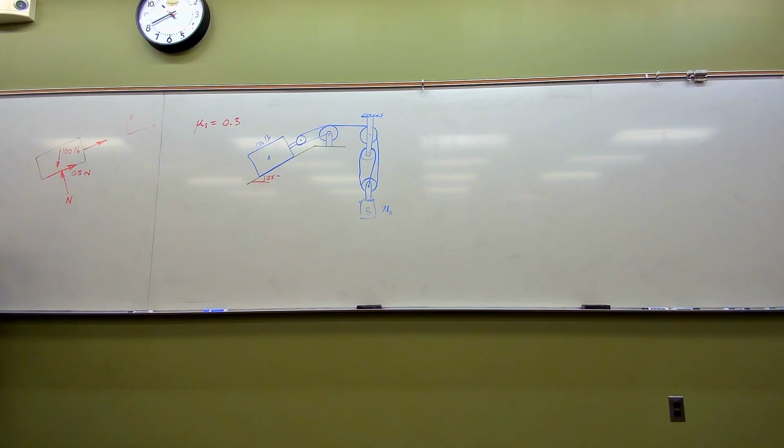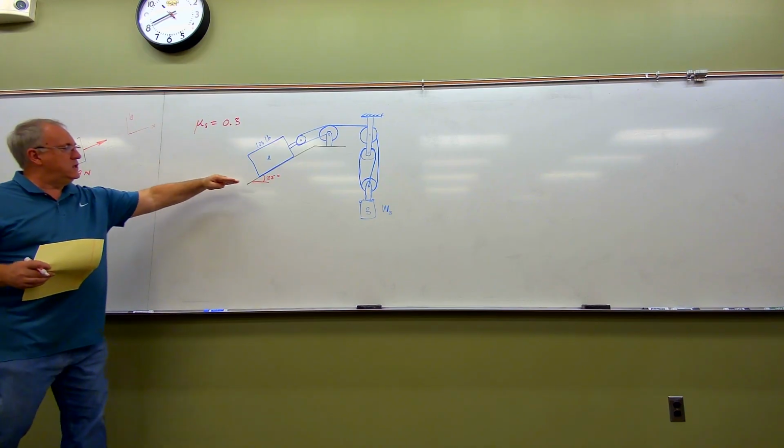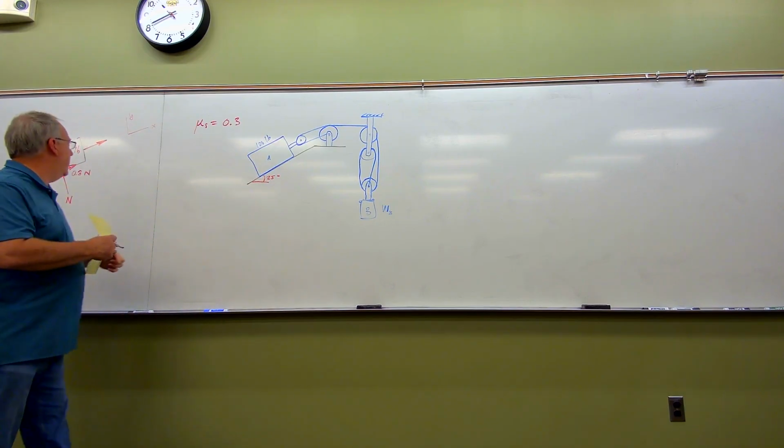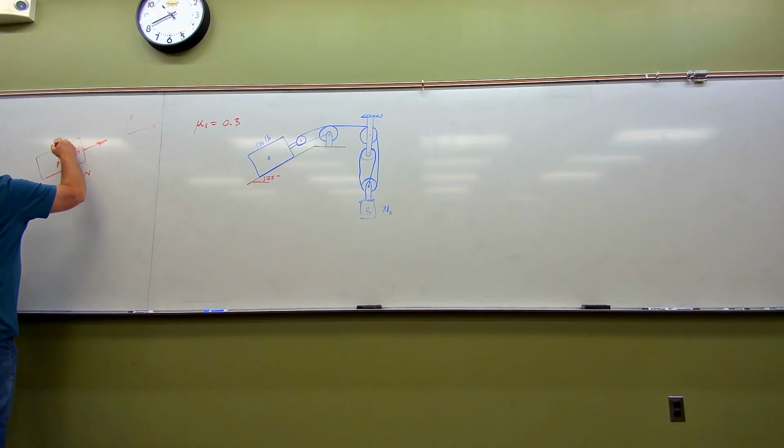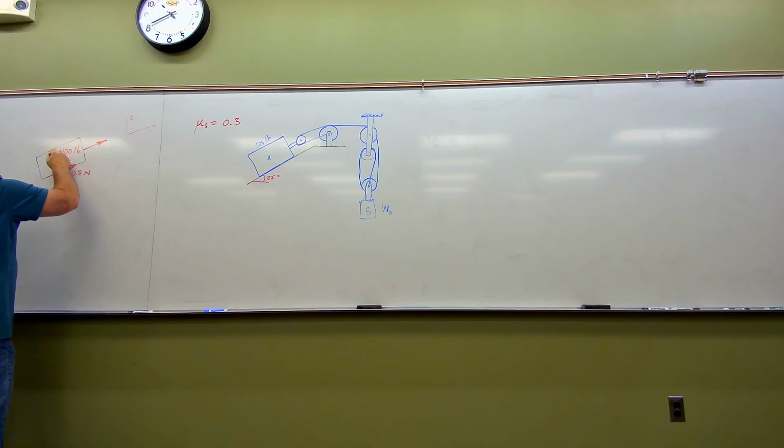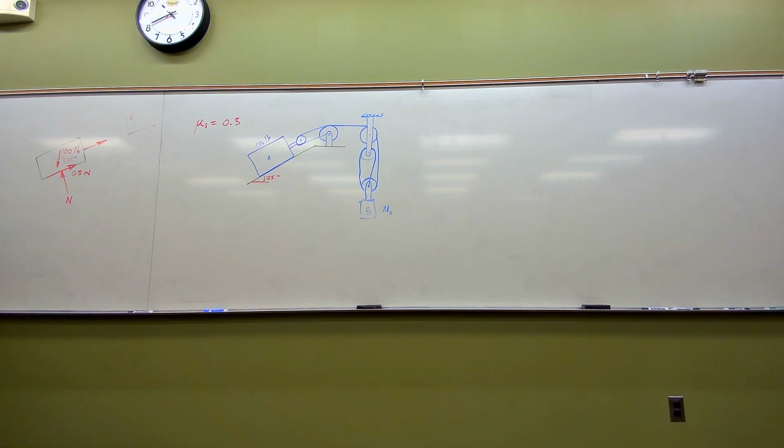And we're going to be able to deal with that because look, if this is a 25-degree incline right here, then this angle here, with respect to my y-axis that I'm about to draw in right here, this angle has got to also be 25 degrees. So, okay, let's roll with that. Now, we still haven't come to, well, what's this force here going to be?